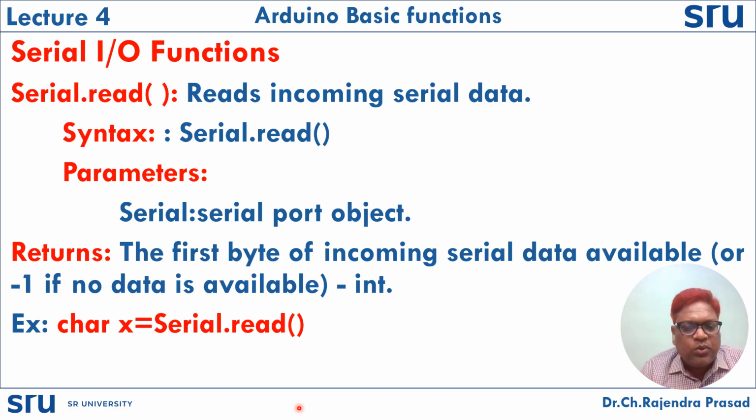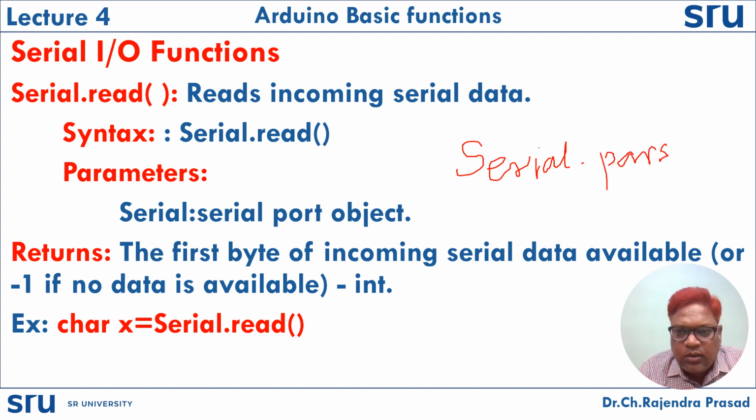And suppose you want to read integer values, in that case you need to use Serial.parseInt. Serial dot parseInt, with a capital I. This function is used to read the integer values.